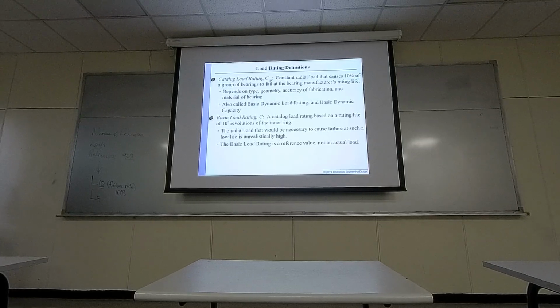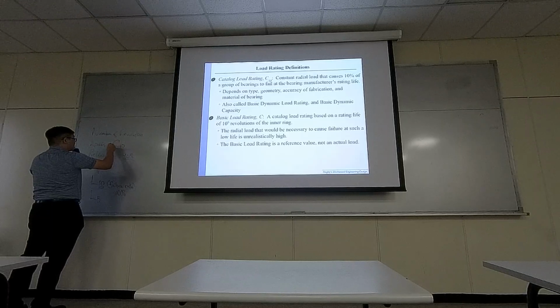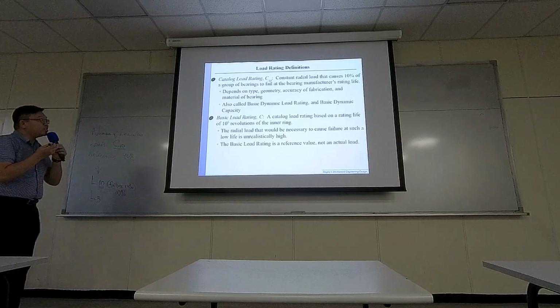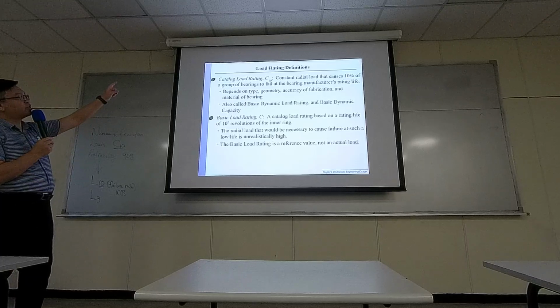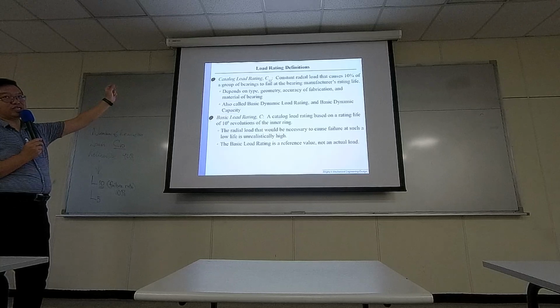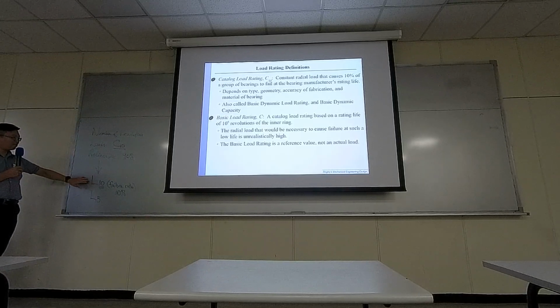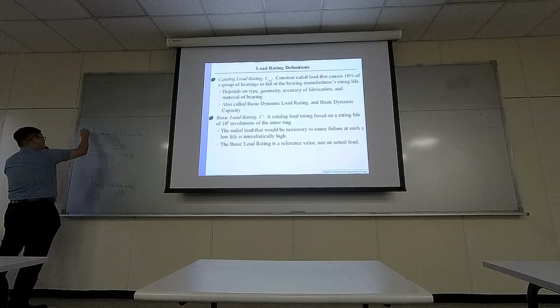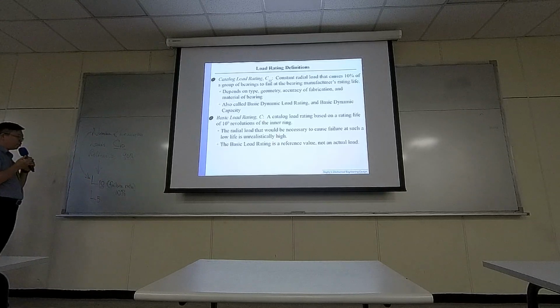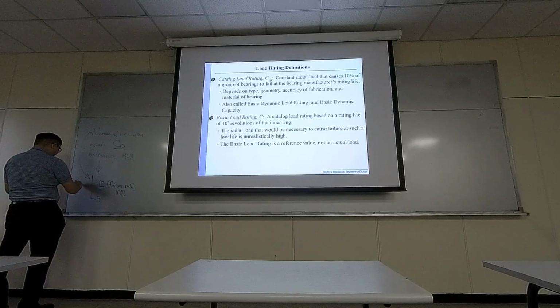So there's also a number called C10. C is going to represent the loads it's going to carry. L represents life and is in the unit of revolutions.